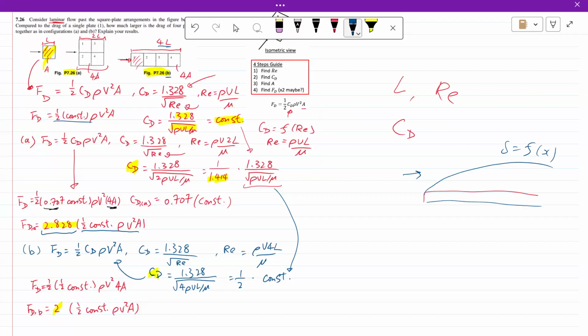So the further it goes, the near wall effect, the viscous effect, becomes more and more significant, slowing the flow down. And because of that, the drag force actually decreases the further you go on. And in case A, you have actually double the leading edge, right? So that's why it has more drag compared to your configuration B.